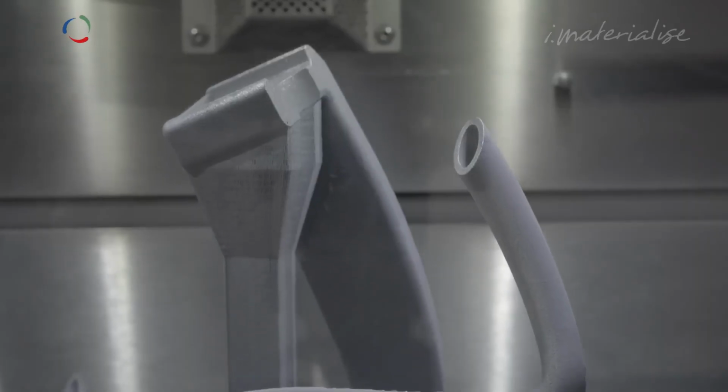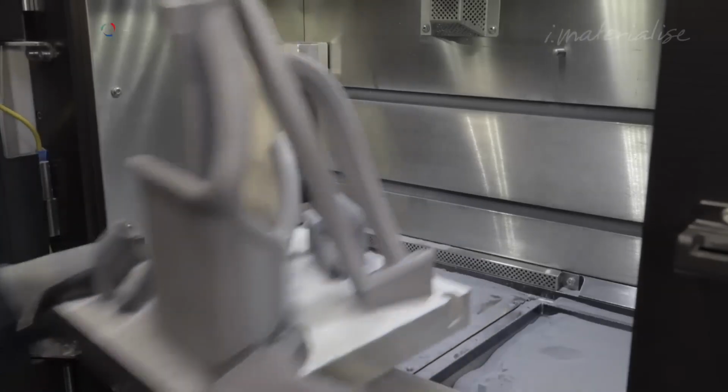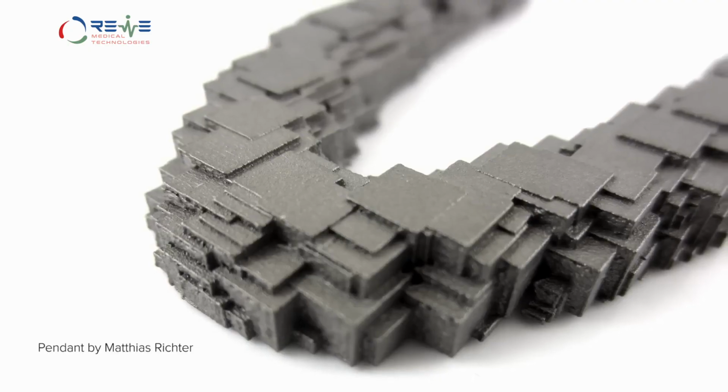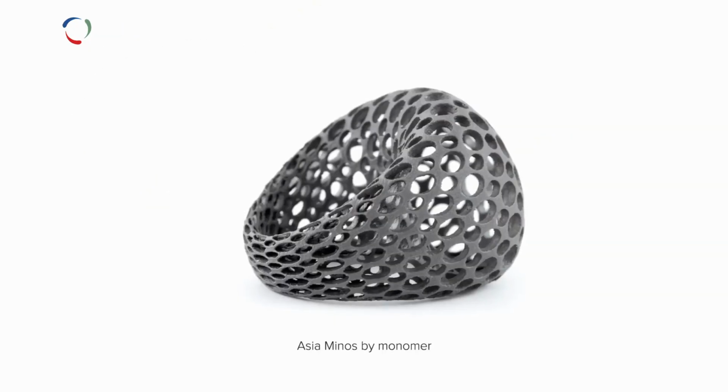And you can see it has very fine parts coming out, very strong parts, but again, they require a lot of finishing. Sandblasting is one of the very critical processes. Most of the machines that you buy have the sandblasting system already integrated inside, because you don't get finished parts properly. And sandblasting is the only way you can go inside those small crevices.